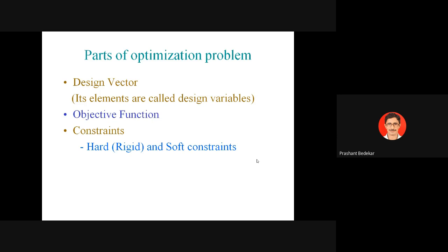Out of this, we being electrical engineers know that the voltage constraint is a soft constraint. If it is 440 volts, and finally after designing the motor I recalculate what the input voltage line to line should be for these parameters, and I get 445, I say okay, my design is fine, no problem. It was asked to design for 440 volts input, and I found it will work properly on 445 volts. Doesn't matter. Voltage constraint is a soft constraint.